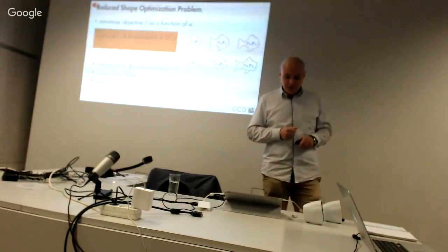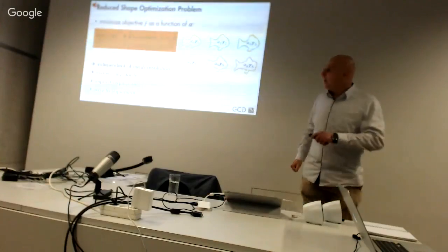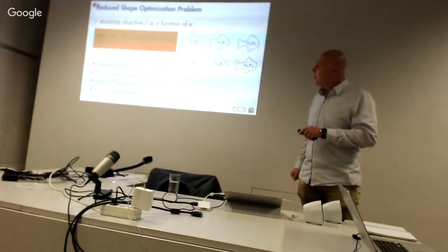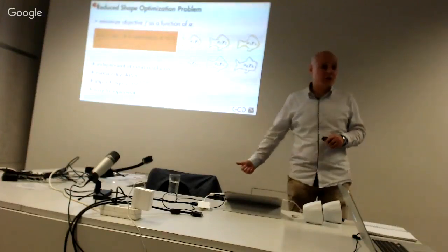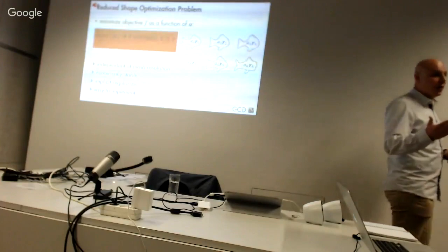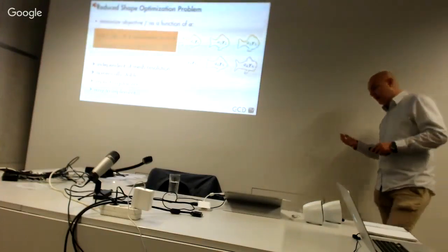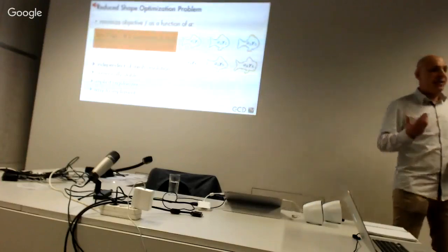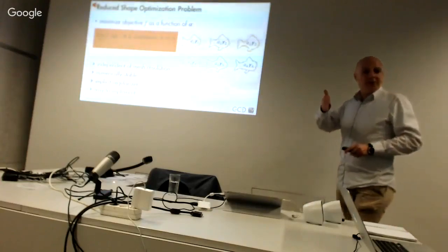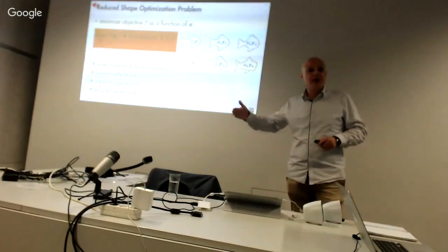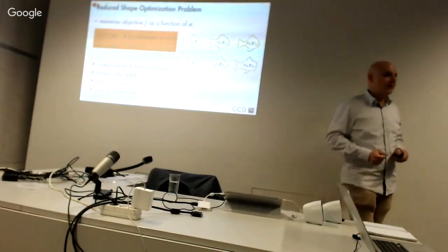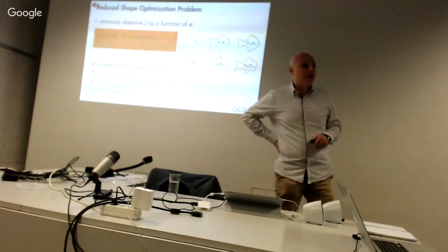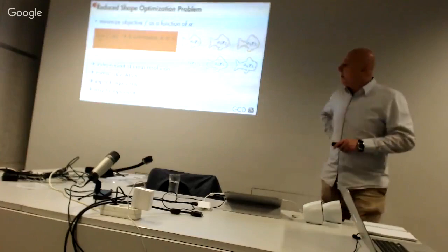Additionally, there are also other benefits. First of all, we are independent of the mesh resolution. Because we have to solve the eigenvalue decomposition, but this is a sparse matrix, and we can use sparse methods where we can aim only for a certain number of k eigenvalues and eigenvectors. So with today's numerical software this is very efficient.